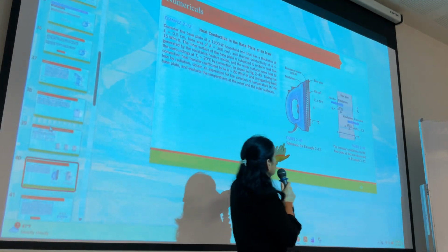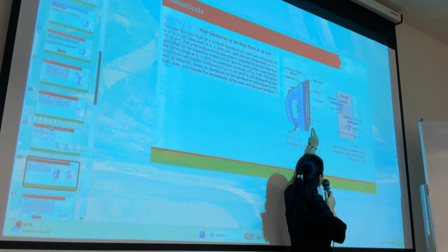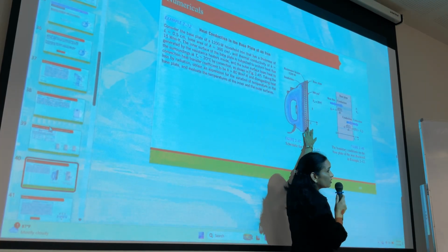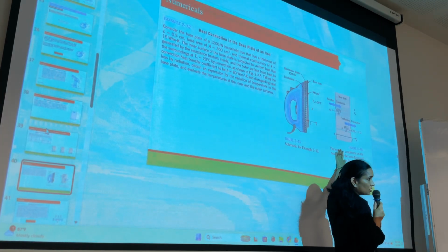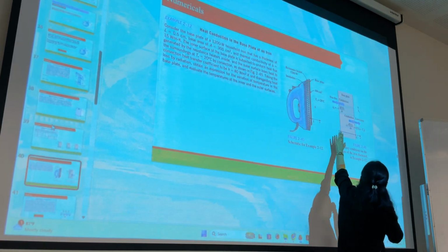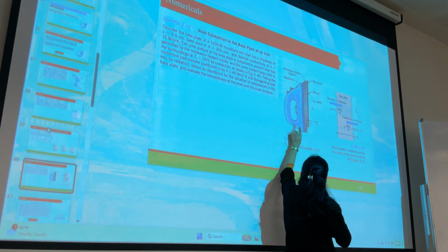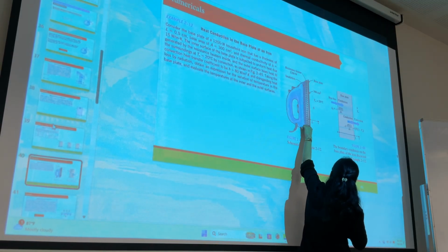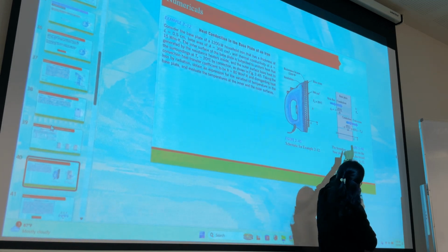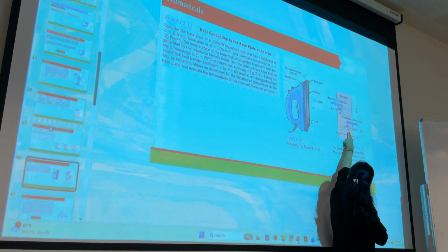This is the iron, and you connect this to electricity. There is a heat flux at this side, and the heat is lost from this side by convection. So this plate you can consider as a plain wall, and this is the heat flux. You connect it to the electricity and heat is generated, so the heat flux boundary condition is applied here, specified heat flux, and the heat is lost outside by convection. Inside this is a solid, so the heat transfer is by conduction.